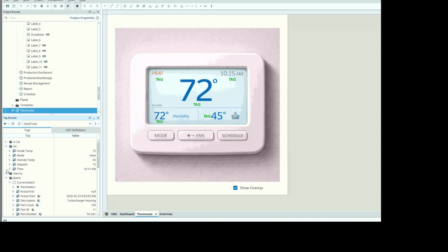the process. If you're looking at a legacy SCADA platform that charges you per tag, let's say you buy a 5,000 tag license, you can pull across 5,000 data points from your PLC within that license. If you want to have 5,001 tags, you need to increase the license. Maybe it's a jump from 5,000 to 10,000. So you're going to at least double your cost, even if you're not going to utilize all of those tags.